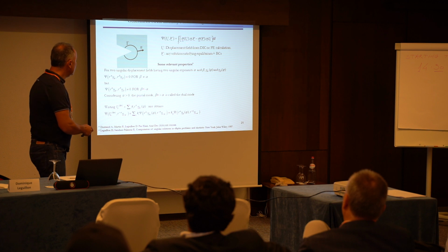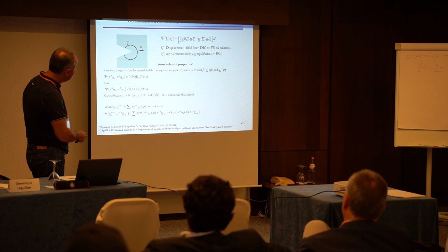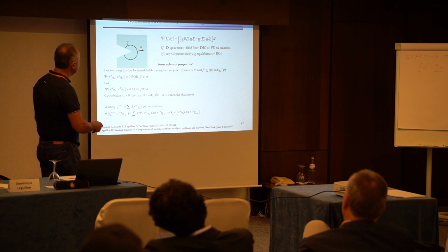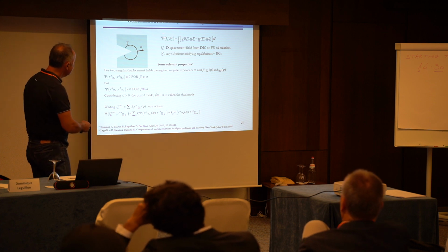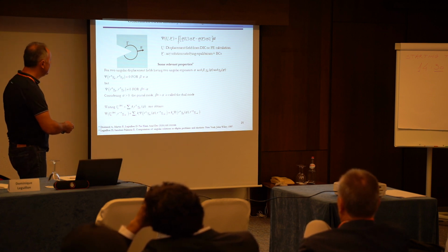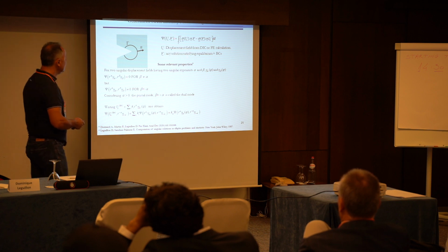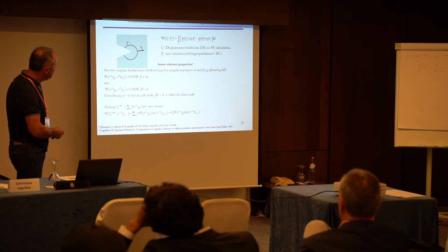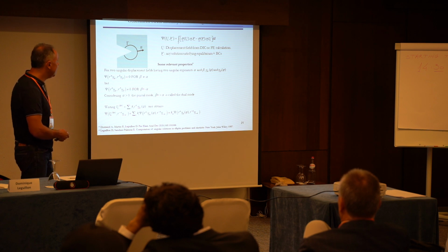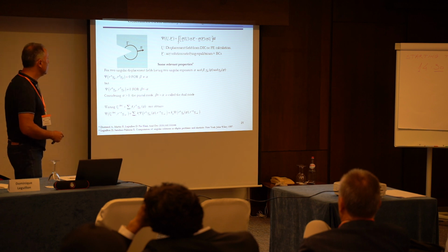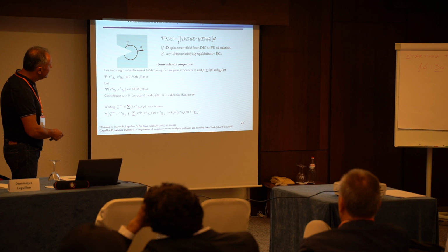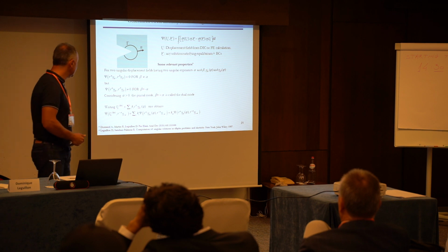And what do you have here? You have a known displacement field and a kinematically admissible one, and Dominique Leguillon has shown that this integral is path independent. So what we are going to use here is that the displacement, capital U, will be the displacement field from DIC or from finite element calculations, as in the paper of Doitrand. And phi is a solution that is going to satisfy the equilibrium and the boundary conditions. So phi is going to be for us the reference solution.